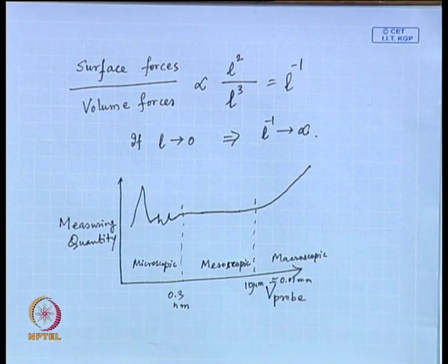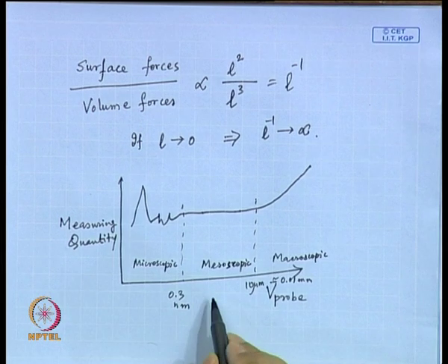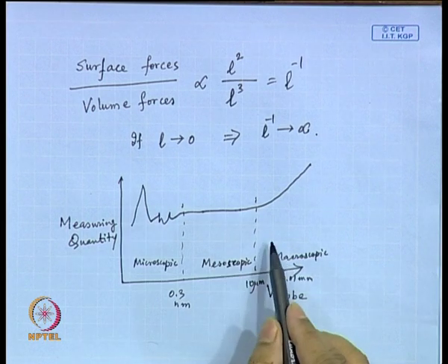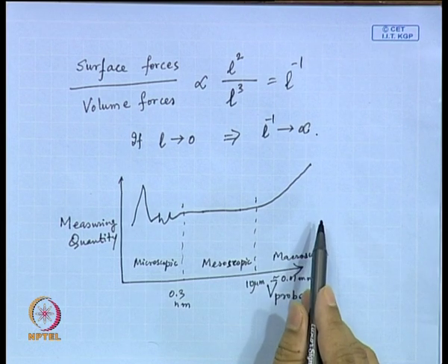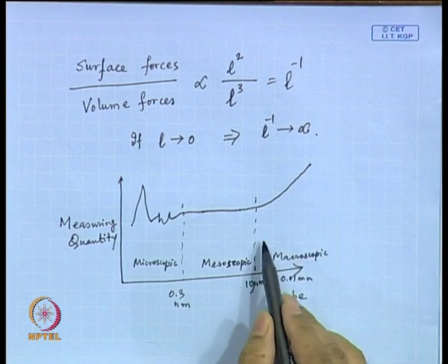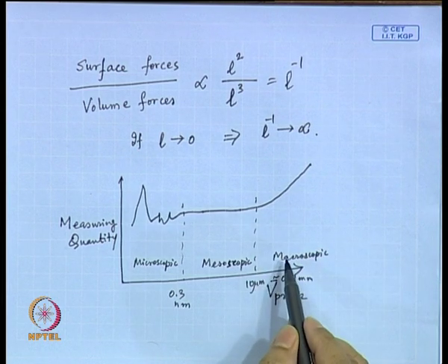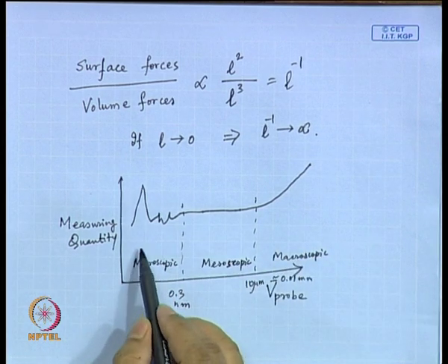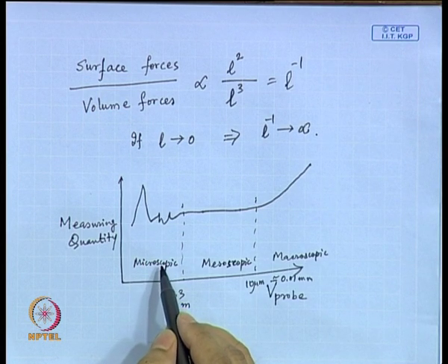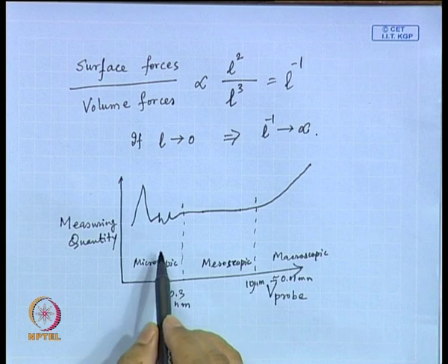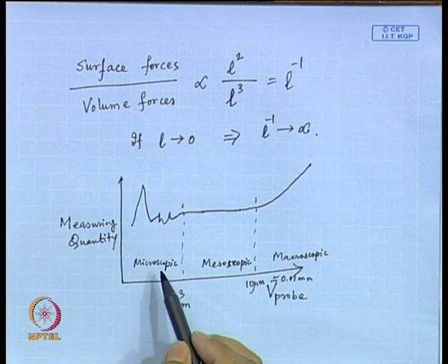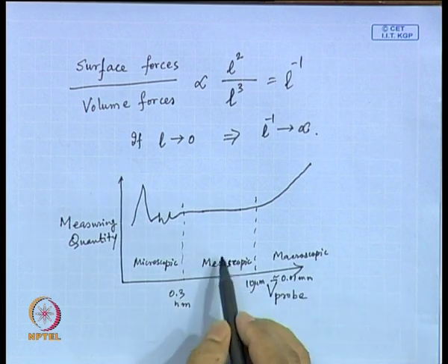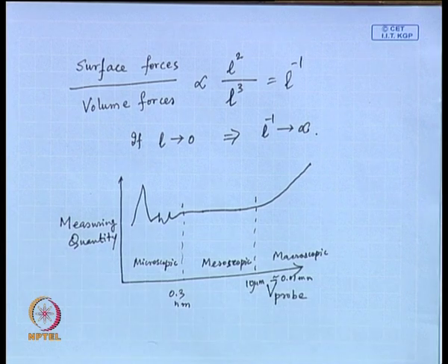So, if you want to know some parameter per unit volume, you should be working in this region, right, because you want to capture whether it is increasing or decreasing with external forces. So, you do not want to work with this region. Your probe volume should not be here, but this part would be just fine. If it is below this, then you will have molecular fluctuations. This microscopic part is very important if you can really gather this information. However, if you are treating it as an Eulerian fluid, then you should be working with the mesoscopic region.